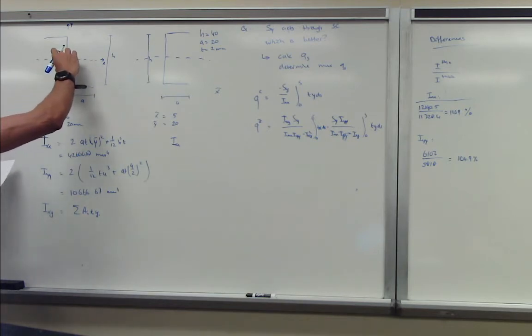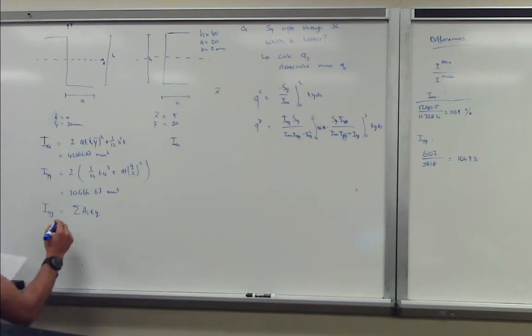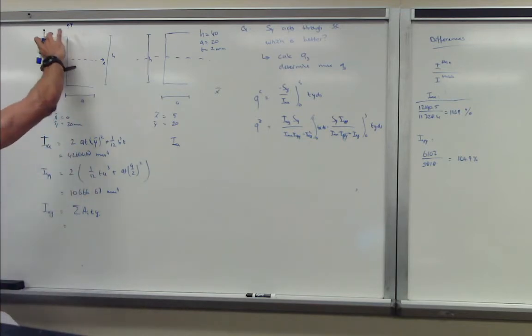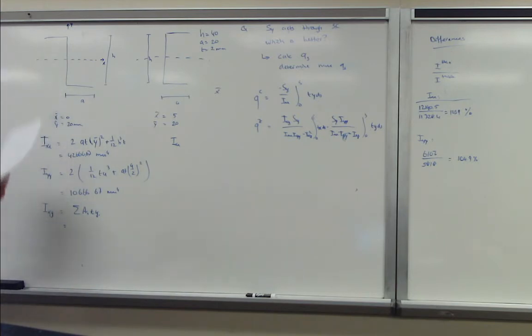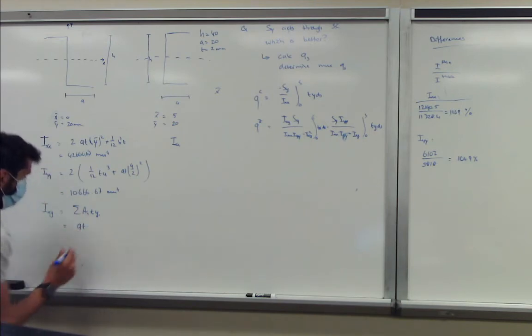In this case, we know that basically the centroid of this vertical flange will coincide with the centroid of the cross section, so that will drop out. So we know that this contribution is 0, so we have these two contributions. And now we can notice that these two basically don't cancel each other out. And the reason is the area might be the same, so we have AT.